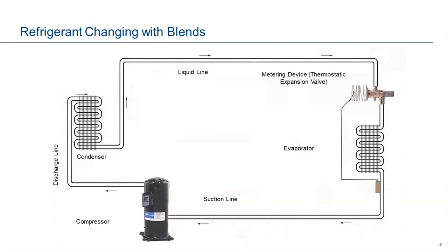We would then open our ports up, obviously, start the system, let it stabilize, and then we're going to connect our tank of gas right here in the suction. Obviously, we can't put it in the liquid line. The pressure would be too high. But then again, we want to be careful here, okay, about putting liquid into our vapor pump, right? Or we'll hear those crunchy noises. I always use the term goose it a little bit. A little bit will go a long way.